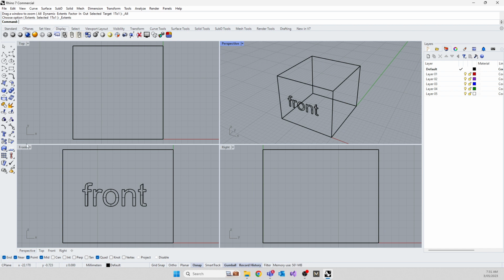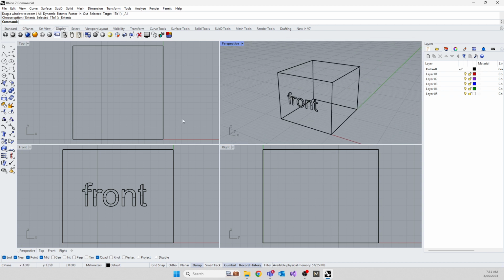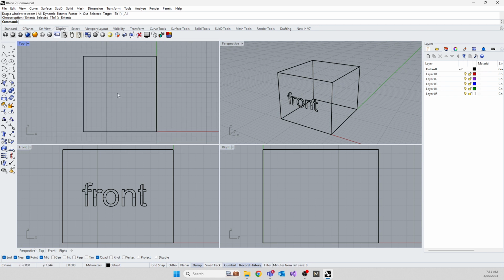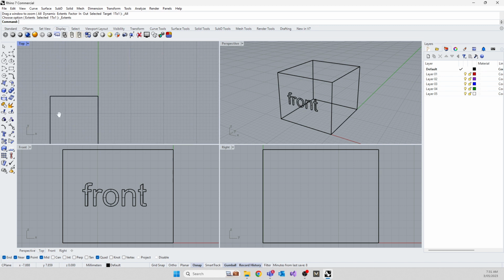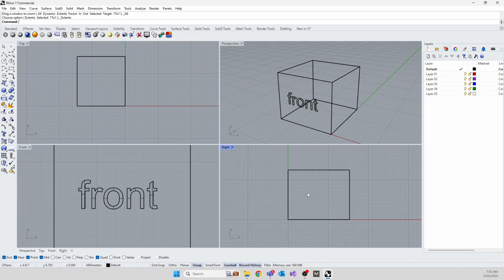Alright. So going through the viewports again very simply, because it can be frustrating how to rotate something. We're going to get onto the perspective viewport in a minute. So you have a top viewport, front viewport, right viewport. Middle mouse button will zoom it in and out. Right mouse button will pan it. Same for these three viewports.